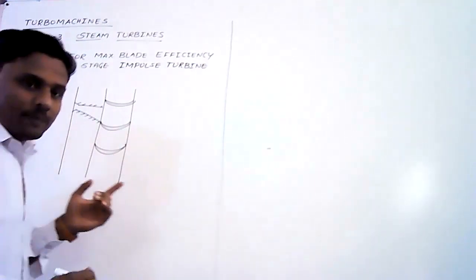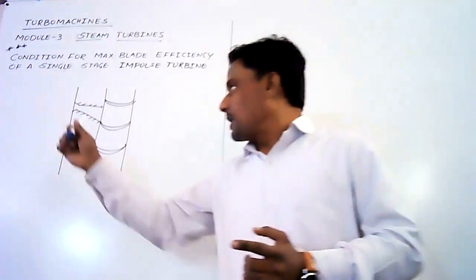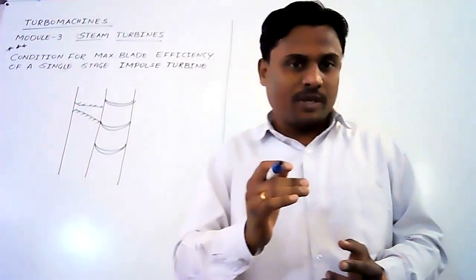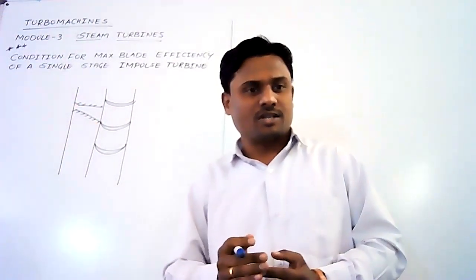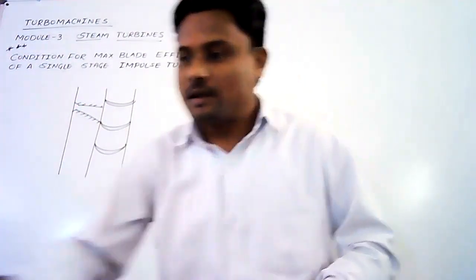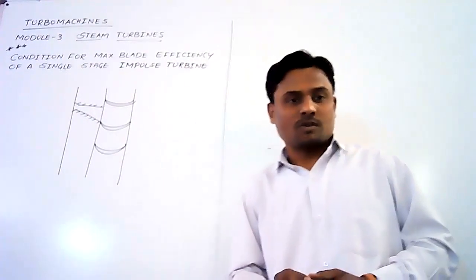The steam at high pressure and high temperature, the superheated steam, expands in the nozzle, where at the expense of enthalpy, a jet with high kinetic energy is expelled out from the nozzle.